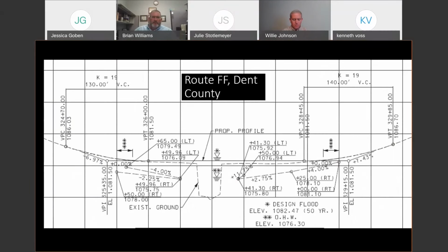So here is the profile of this route. As you can, it's probably hard for you all to see maybe, but you can utilize your profiles that come out of Geopack to determine what your slopes are, to know how many ditch checks you're going to need in your area. Okay, so you've got 2% grades on each ditch over here. So think about utilizing this tool to determine the amount of ditch checks you need based off what the standard plan provides.